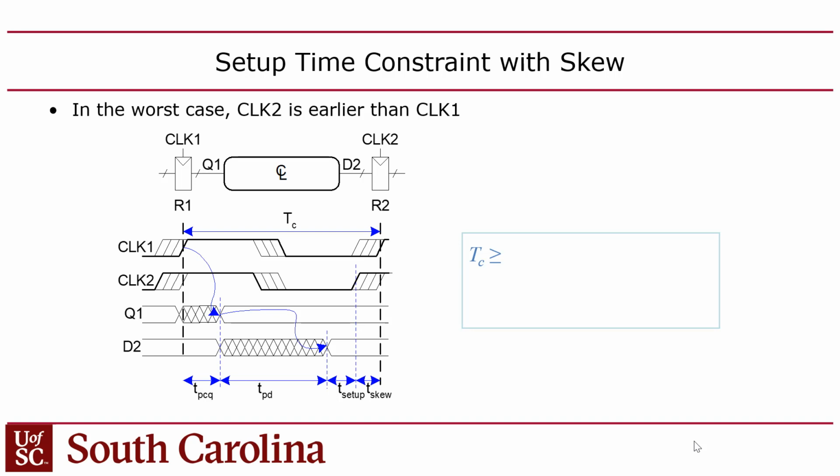You guys with me? So you have to build in a margin in your setup time analysis to account for the maximum skew, clock skew. Make sense? Okay, so what that means is that, well, it doesn't really mean a lot. It just means that you have to add that as another term.